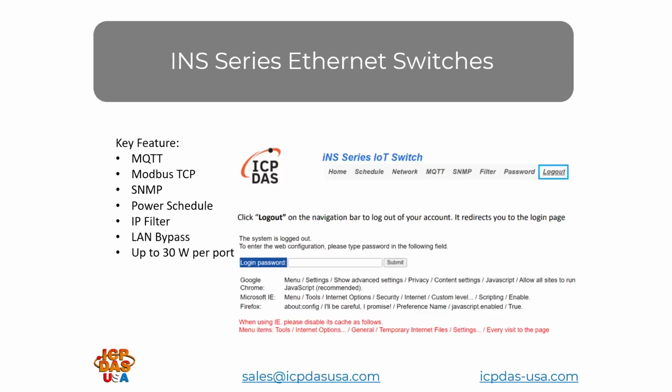It's also password protected. Some of the key features for automation: it provides communication abilities to MQTT so you can share data to the cloud. It does Modbus TCP so you can control different aspects of it. You can configure the module using some Modbus TCP registers, or you can monitor and control the different ports through Modbus TCP. This switch also supports SNMP. You can set a power schedule so that you can, say, turn on lights or dim lights on a schedule. So, for instance, in the morning time, you can turn the lights on.